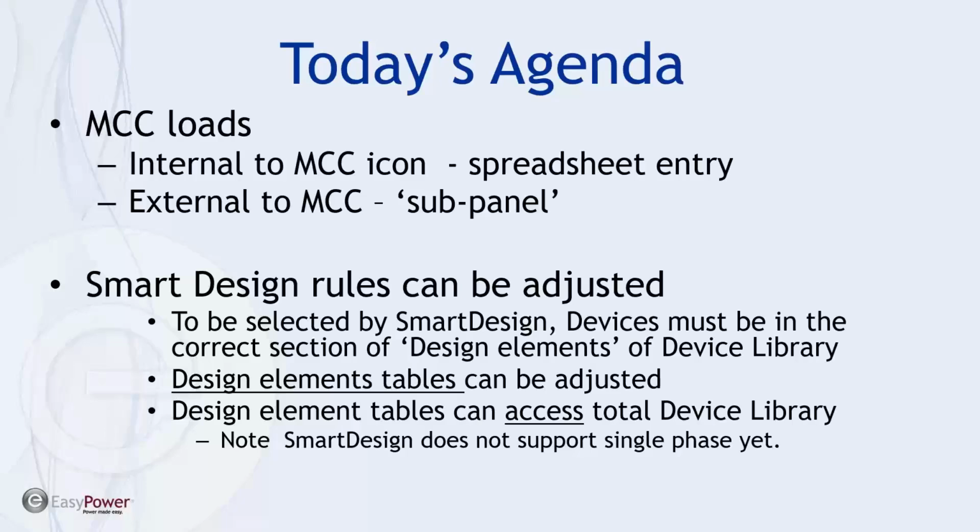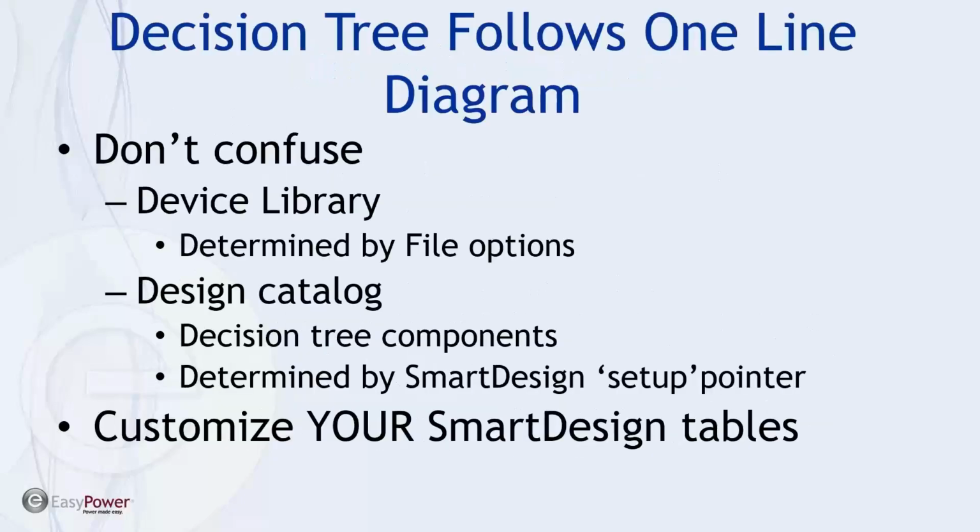Well, the point I'm going to be trying to make is that the SmartDesign is not an all-knowing magic wand. It must be directed based upon the guidance that we provide in the setup, plus the way it utilizes the lookup table in the device library. All of these elements can be adjusted, and the more we know about that and how it applies to what we're trying to achieve is kind of at the heart of where I'm headed today.